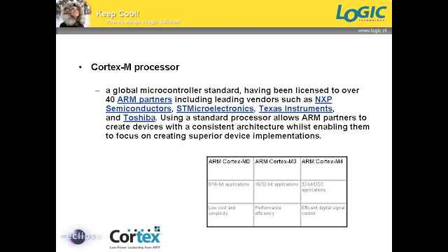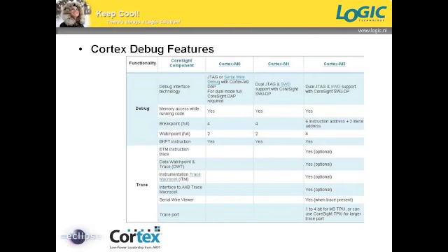They license the core, develop, manufacture, and support the end user. Besides power management, CoreSight enhances the real-time debug functionality. A new software standard called CMSIS was added to provide a new mechanism to access the internal peripherals. This will ensure better usability of software and replacement of processors in the future. Finally, a 2-wire interface was added to reduce the pin count.